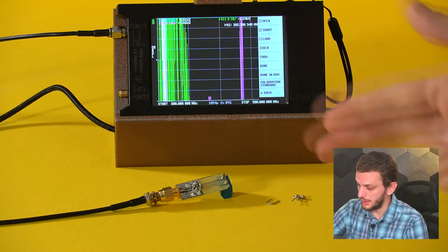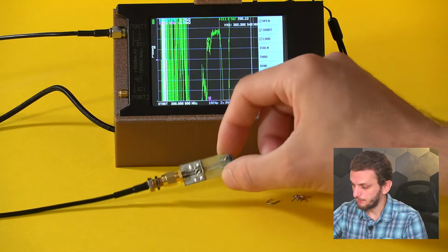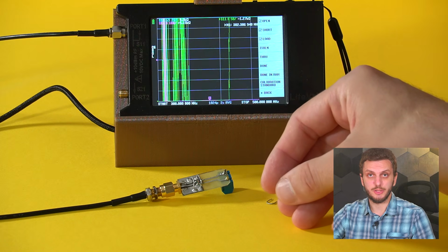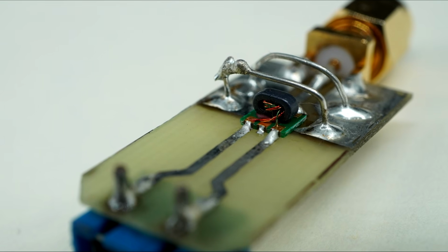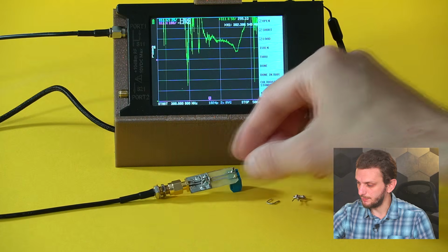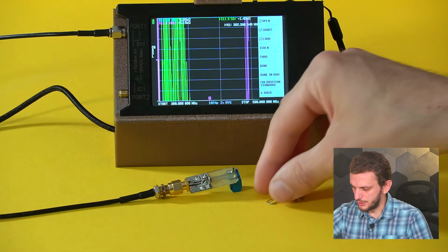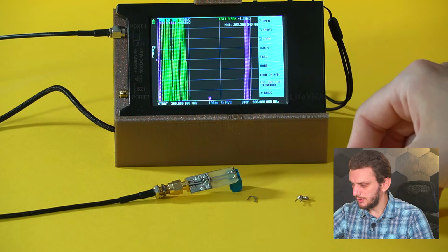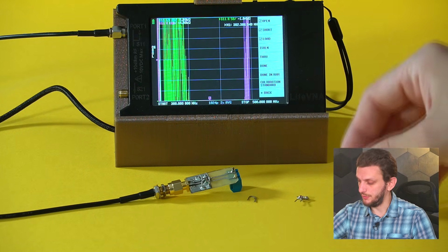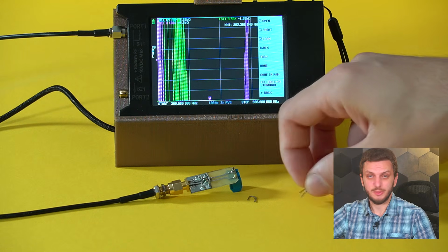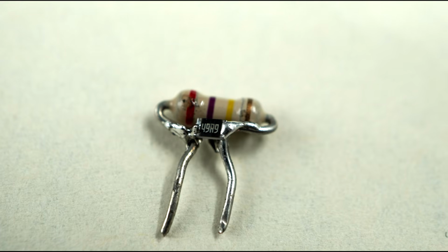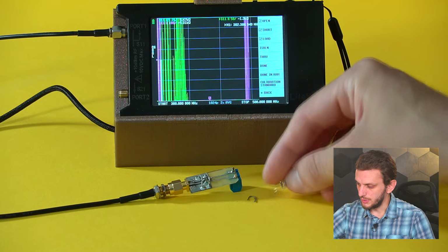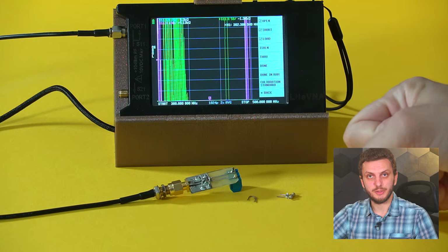So today I will be using a 1:1 commercial balun, which is rated for a frequency interval of 5 MHz to 1 GHz, and I mounted this on a small adapter board in which one side is an SMA connector and the other is a connector into which I can plug my antennas in. Now, to perform the calibration, open circuit and short circuit is not that difficult, but to perform the load calibration, so the 50 ohm, to have as resistive a component as possible, I took a 50 ohm SMD resistor and soldered it to a large value through-hole resistor. So this will be inserted to perform the load calibration.